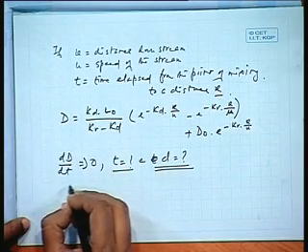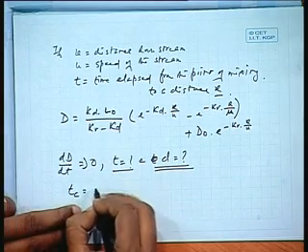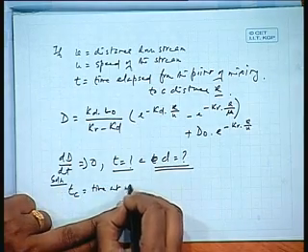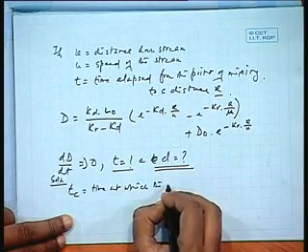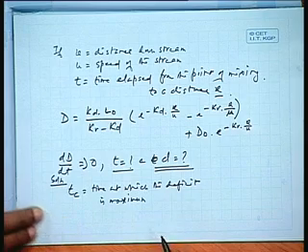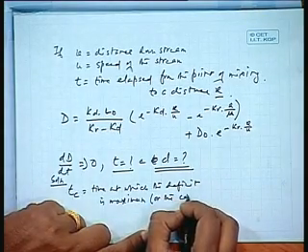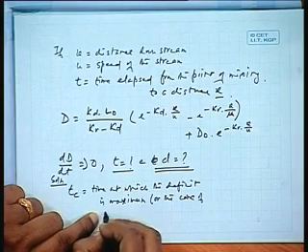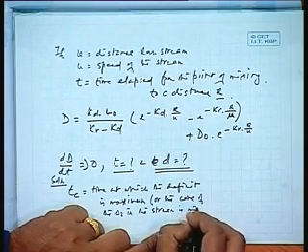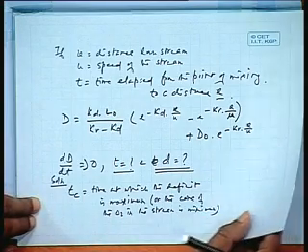In such cases, a simple solution is T critical, that is, the time at which the deficit is maximum, or the concentration of oxygen in the stream is minimum. It can generally be found out like this.